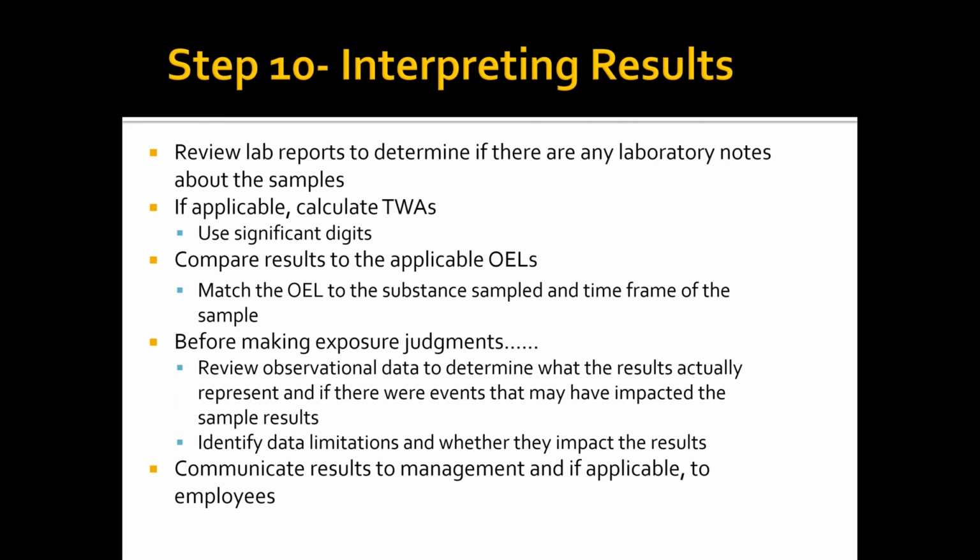Make sure you're comparing it to the correct OEL. Review your observational data to figure out what the results represent, and if there are things that happened during the shift that could have impacted them. When I write reports, all of that's in there so that somebody reading it can go, oh boy, that was way different than what's normal. Maybe we should resample that again.